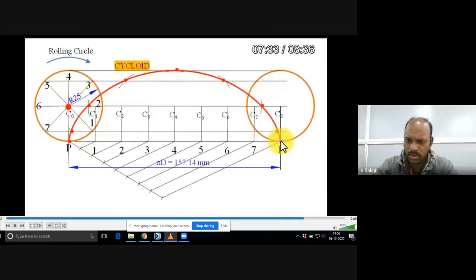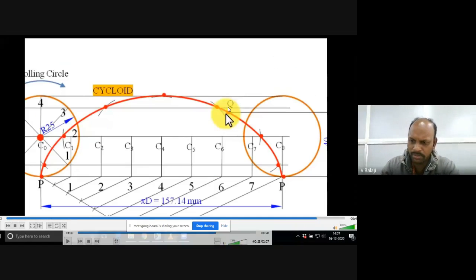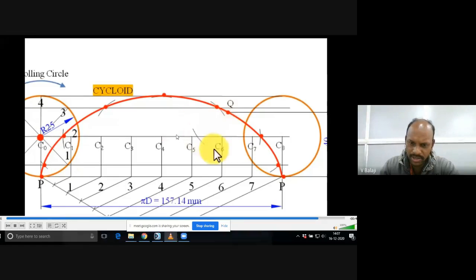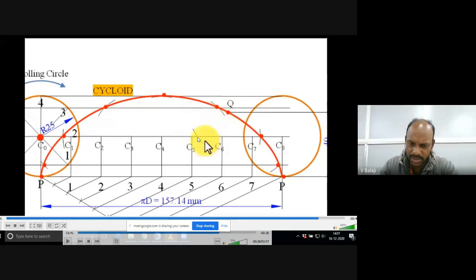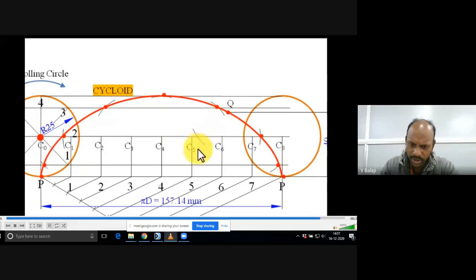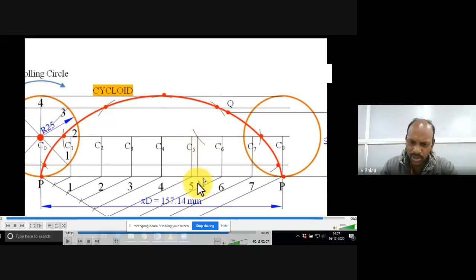For the normal and tangent also, you can choose 40 mm height. You take any point Q. That point Q must be 40 mm height from the ground. Now take your compass, set radius 25, and cut the center line. From that center you would get one point here. Drop down one line vertically onto the ground. Thereafter, you join this point M and Q. That is the required normal.